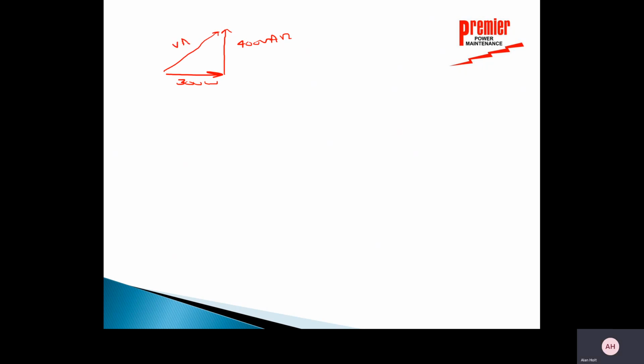So the first question is what's my voltamperes? Well, I can use Pythagorean's theorem. I know that the voltamperes is equal to the square root of 300 squared plus 400 squared. And so that equals 500. So my voltamperes for this power triangle is 500 voltamperes: 300 watts, 400 VARs, 500 voltamperes.